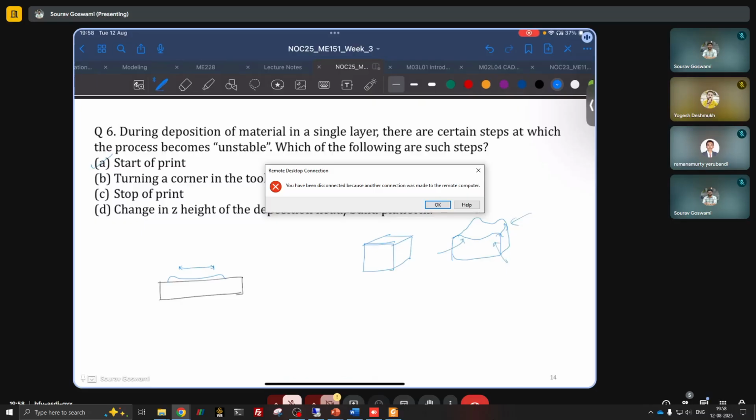And the reason for this is because in two dimensional CNC, we are coming along one direction and then turning at 90 degrees and then going in some other direction. If we do this at constant speed, because of the change in direction, there is still some acceleration, or deceleration, as the case may be.